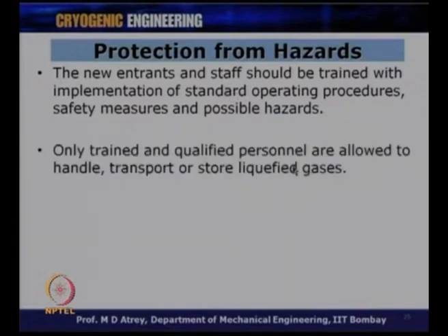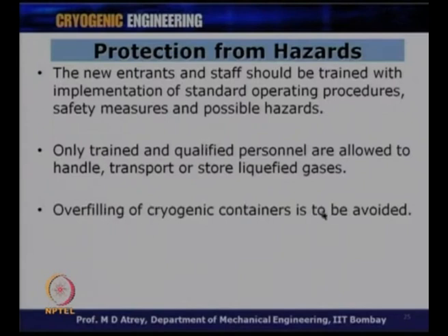Only trained and qualified personnel are allowed to handle, transport or store liquefied gas. This is very important. Training is a very important component, to teach them the operating procedures of handling such cryogens. Overfilling of a cryogenic container is to be avoided.